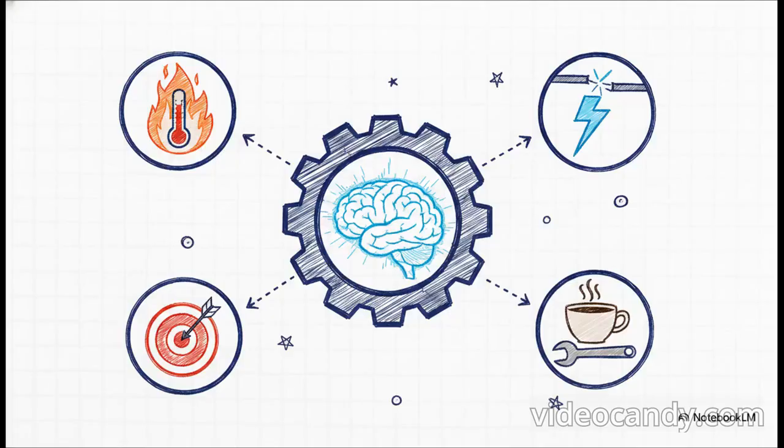So the big takeaway here is that we are turning raw data into actionable industrial intelligence. With IO-Link, you're getting early detection of impending heat collapse. You get immediate short circuit warnings. You can even monitor internal sensor drift to catch a component slowly falling out of calibration. There are even lost frame counters to help diagnose those really annoying wiring or electromagnetic interference issues.